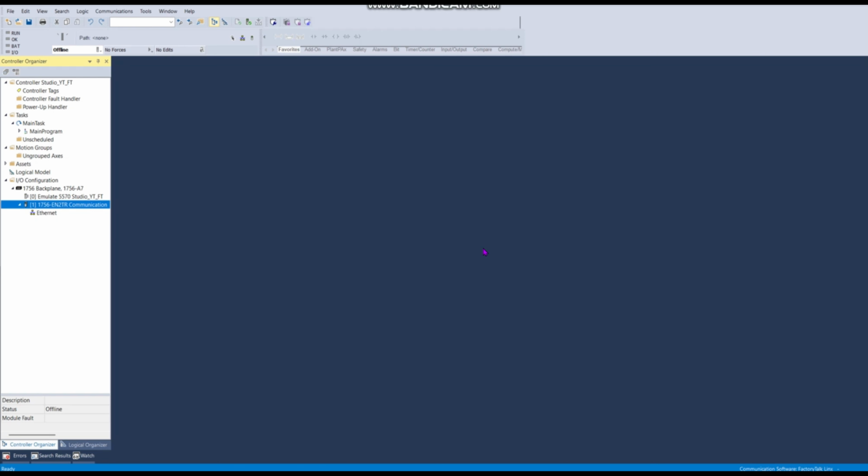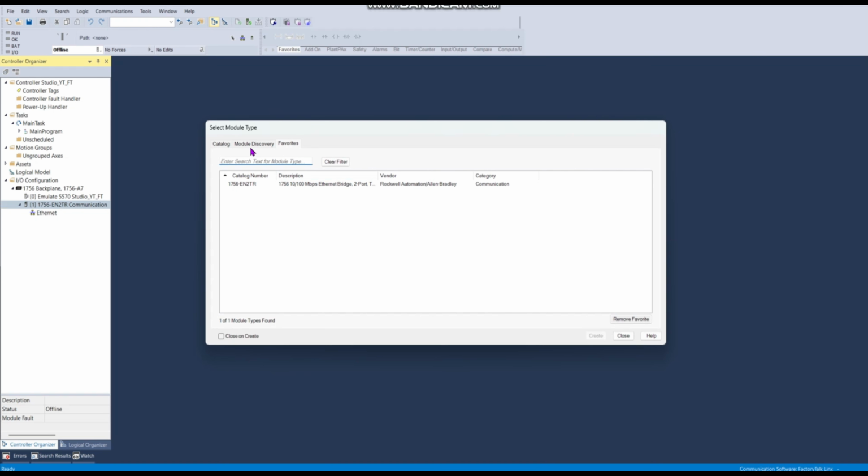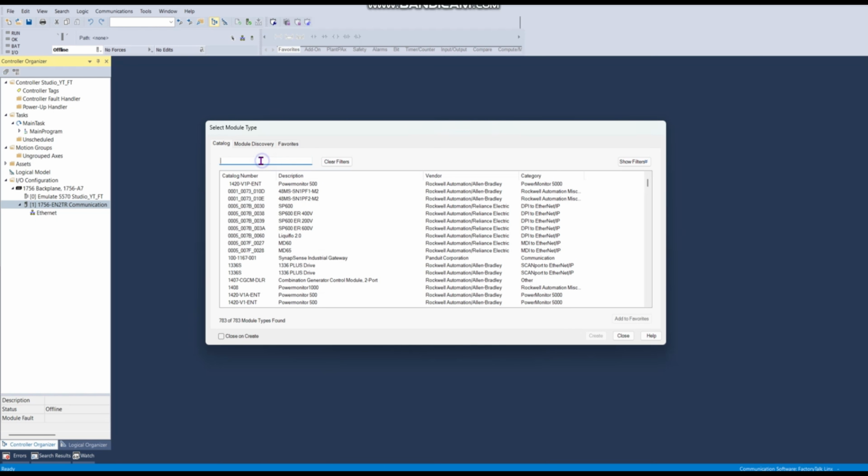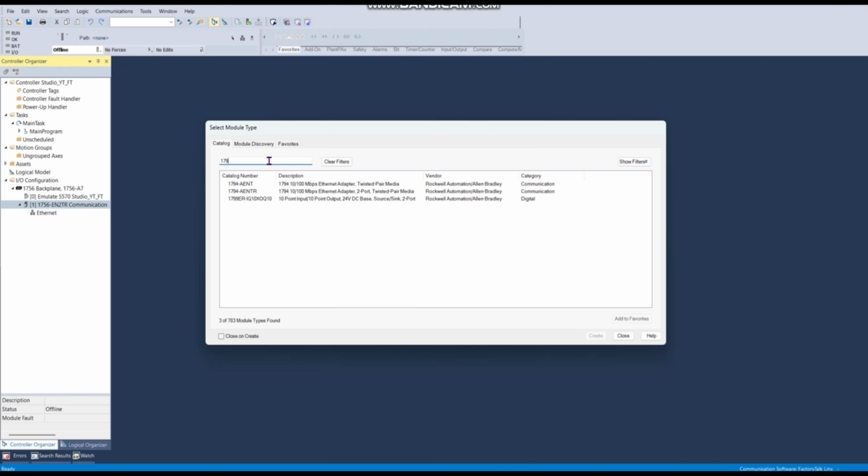So next, which communication card you need to select? You can select the 1794 category. But please remember, Rockwell has now made the 1794 series obsolete, and they make the 5094 PLC, 5094 communication card, and also 5094 Flex IO. In Rockwell they are using two types of IO. I will discuss that later.